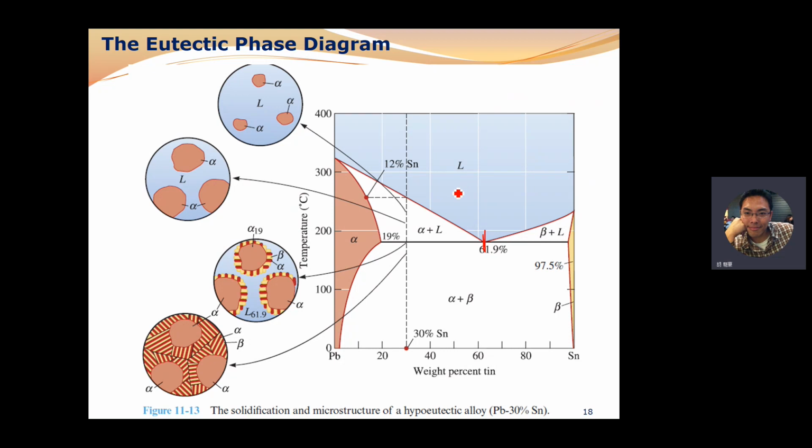And what's the definition of eutectic reaction? Do you guys still remember that? The reaction at this composition, I mean, one liquid solidifies into two solids, right? Two solids. And on its left, it's called the hypoeutectic. Its right is hypereutectic.